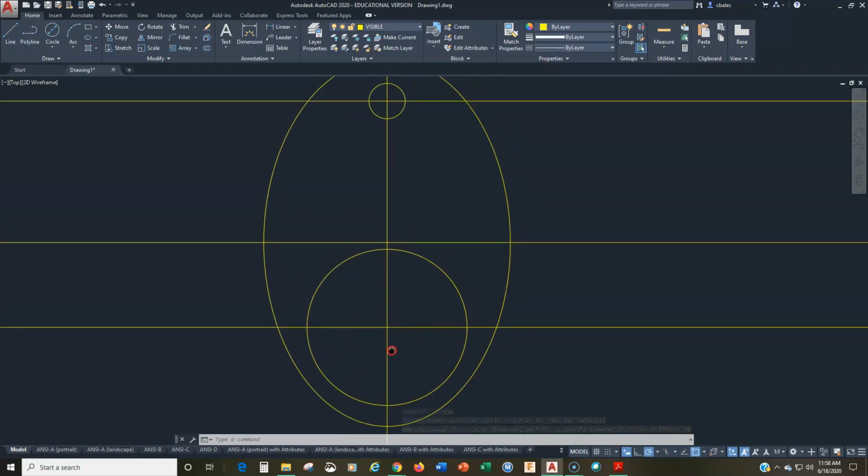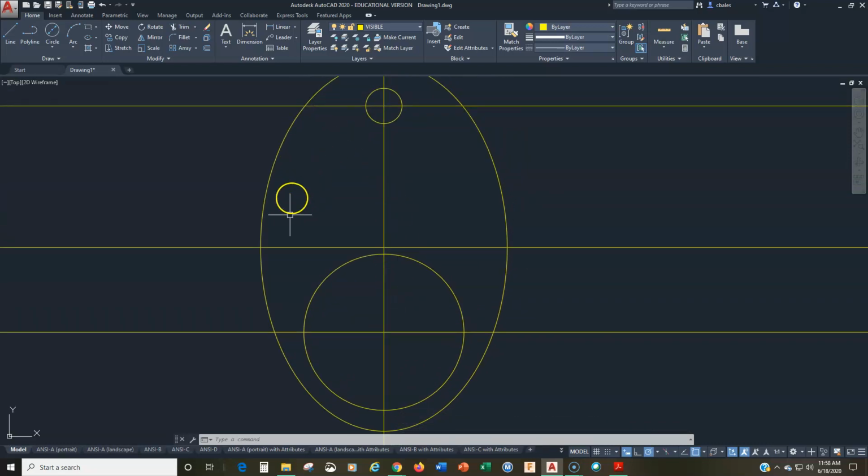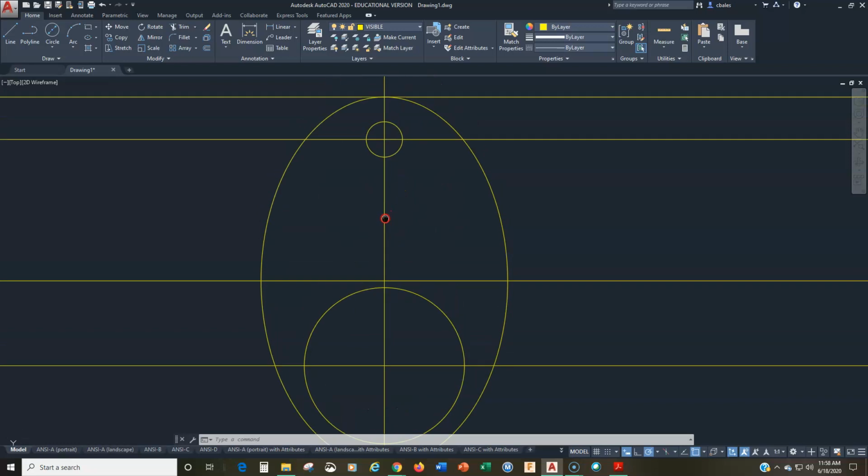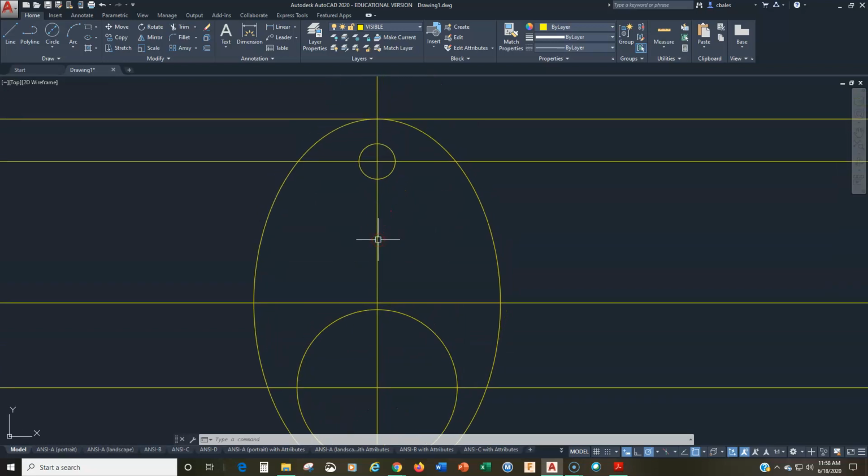Okay. We'll leave the polygon for later, but let's work on this part. So let's first draw the circular features. I'm using the term circular features because we're going to trim them. Circular features with a known center, because we can get those in. So I'm going to go to center radius, and I'm going to put a circle in here with a radius of 0.75. Okay, right there.